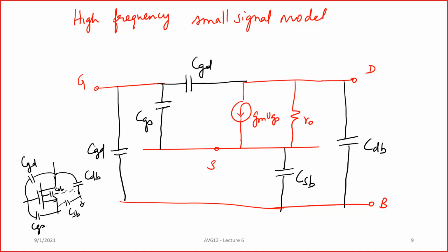So when you are looking at low frequency analog design, you really don't consider so much of the capacitance. You only look at the output capacitance, and of course you do look at it for the sake of calculating bandwidth. But in the case of RF circuits, like how some of you students had taken the elective in the previous semester, we consider the CGS, CGD and all these things very seriously. For low frequency circuits, you don't consider so much when calculating DC gain and low frequency gain. Of course, when you want to calculate bandwidth, all these capacitances come into the picture.